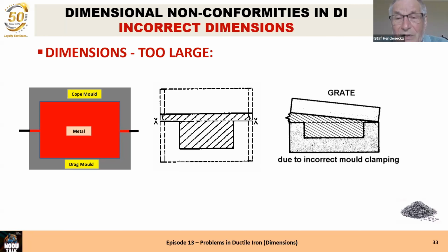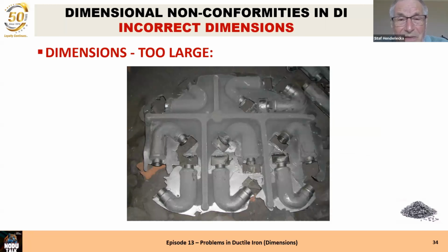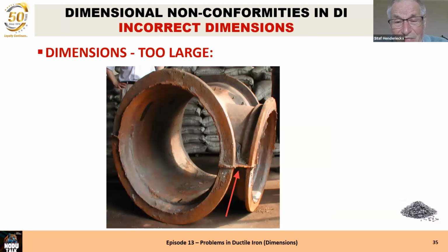Also putting weight on a mold is important, because the weight must, let's say, cover the whole area of the mold where the casting is below. I don't know if you remember something like this. I see it so many times. Don't think the dimensions are okay with a flash like this. You can forget it. It will be a different dimension. And mostly the dimensions will not meet the requirements as they are put in ISO 8062. You see from time to time flash of up to 5 to 10 millimeters sometimes.